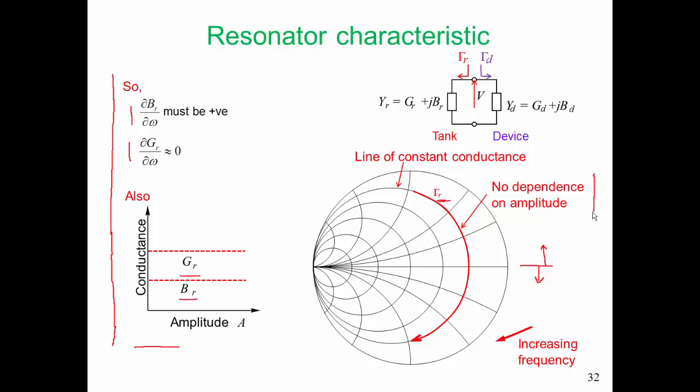During the design of the resonator network using CAD tools, we can test this as well. We can drive the resonator network with an active port, change the available power from that active port, and see if gamma R will change with amplitude. Now you may be thinking that we're going to design a resonator network that is passive. How could the amplitude change?